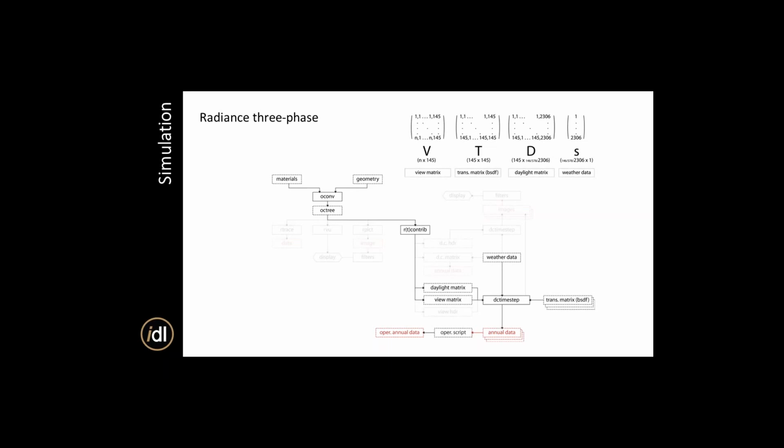And then we would apply the actual weather data and whatever complex fenestration system we would want in that particular case. And that would give us 8760 hours of data for essentially each combination of these two. So whatever fenestration system you want and whatever TMY3 climate you would like.